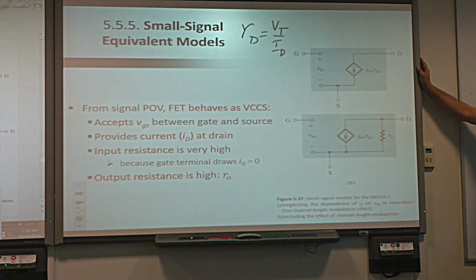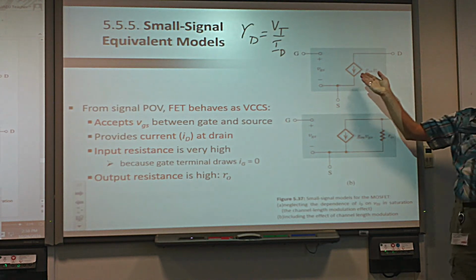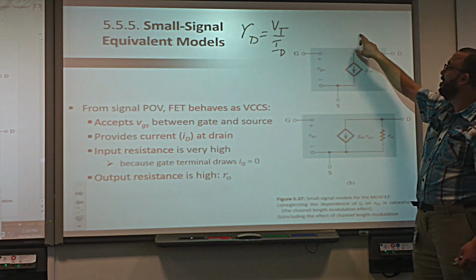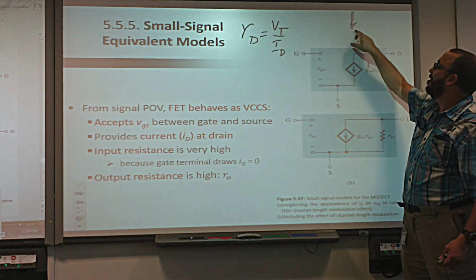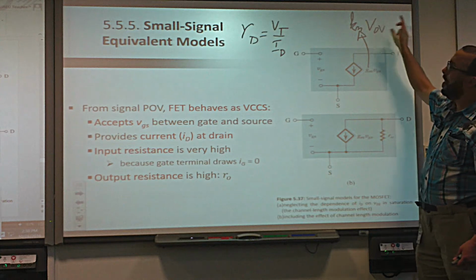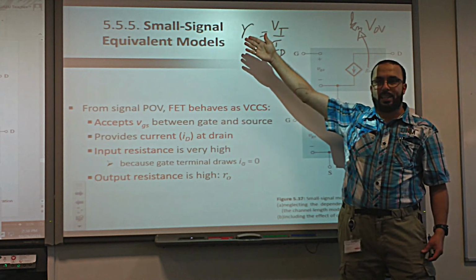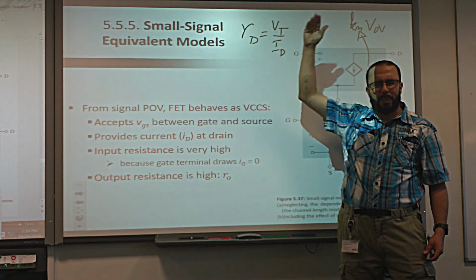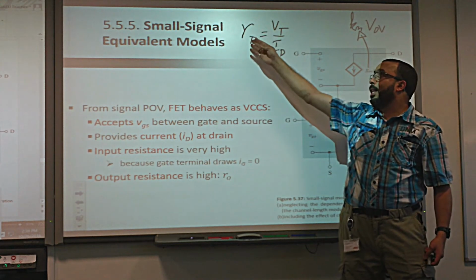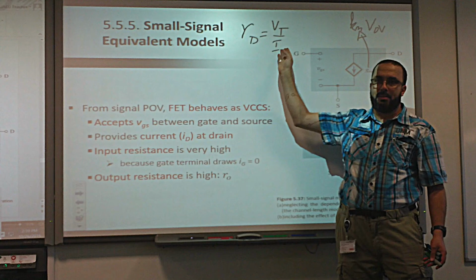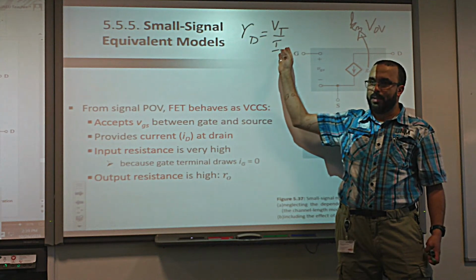Very similar. Because when we did the small signal analysis, we found gm, remember? How much is gm again? Kn times V overdrive. Very simple. So here, we replace the diode by a resistor that depends on the DC values of the current of the diode.